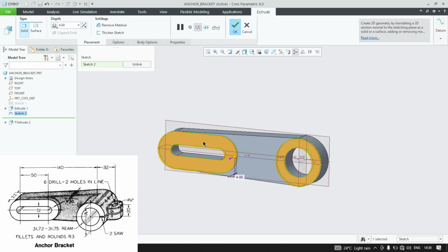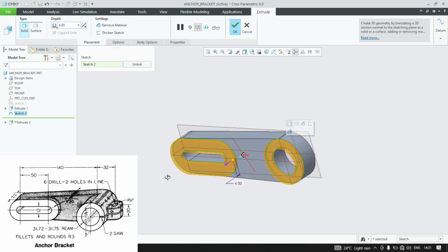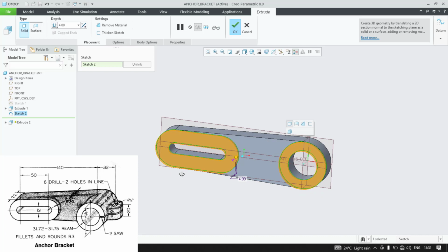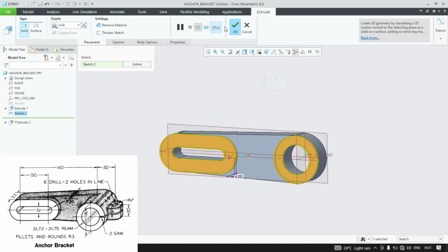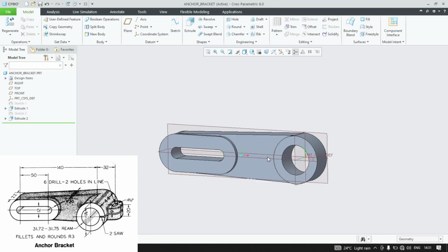Okay, I think we don't have the contour selection to just extrude only one portion. I'll get back to that if it is there in the data sessions. Okay. Yep, I'll extrude it up to 4 mm and later on I'll create one more sketch to extrude this side circular boss up to 44. So we are already done with 22.